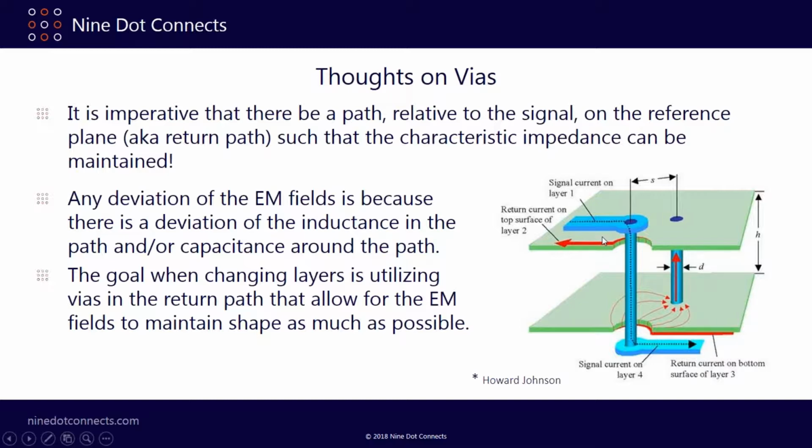And again, your transmission line has a characteristic impedance, which is relative to the ratio of the inductance to capacitance. You want that capacitance to stay the same even as the conductor moves through the stack. So you have to basically create the parasitic capacitances in that situation through that hole.